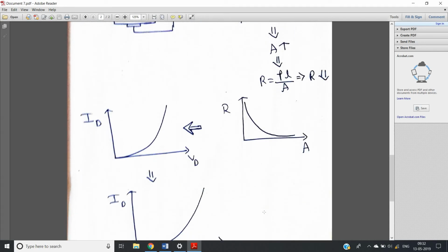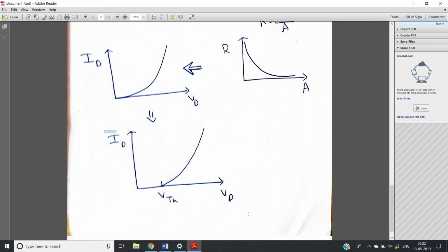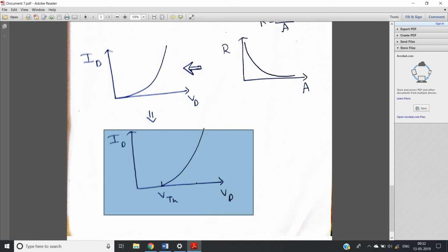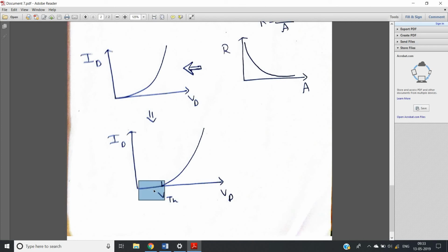If you have a lab in VLSI, obviously in most of the universities in India there are VLSI labs, and obviously in other countries also. So see, from this graph you can do an experiment. Suppose the VTH or threshold voltage for the MOSFET is unknown to you. So how can you determine the threshold voltage? Simple. First you make one circuit where you take one NMOS, you provide the gate to source and drain to source potential properly, and then you plot the drain current versus applied gate potential graph, and you observe up to which value of gate voltage the drain current is 0 or very minimum.